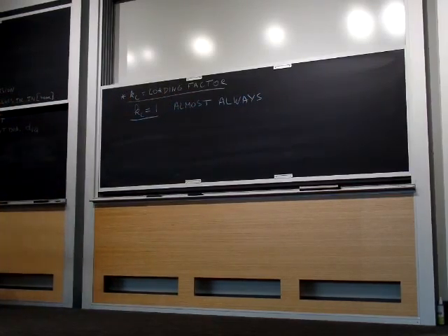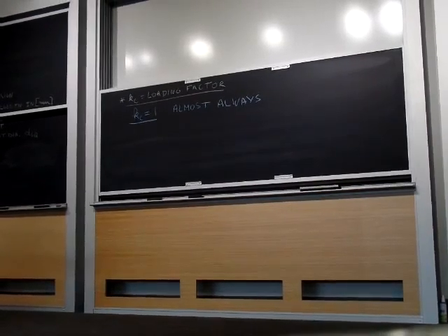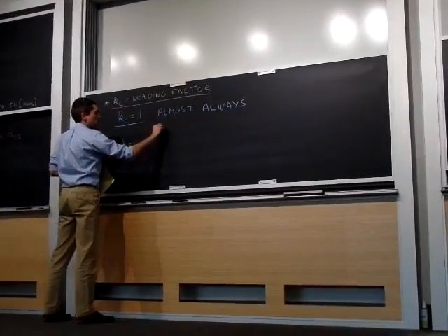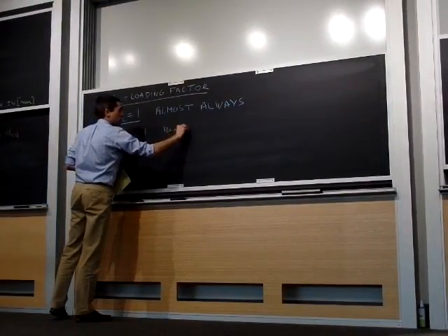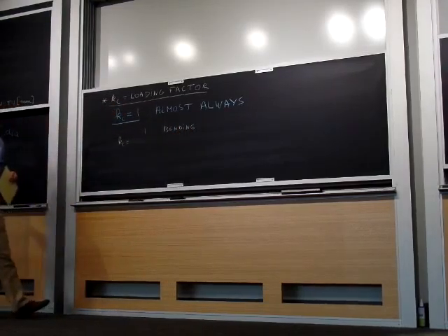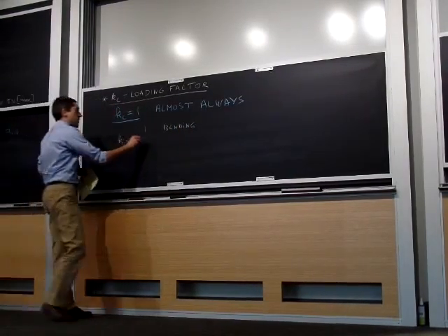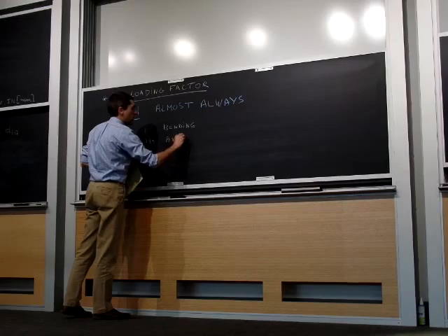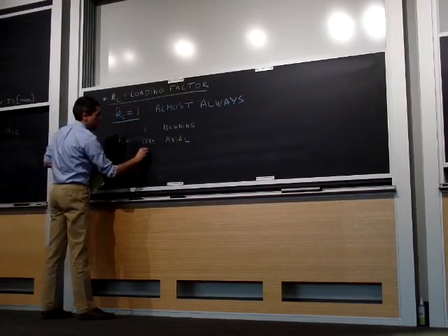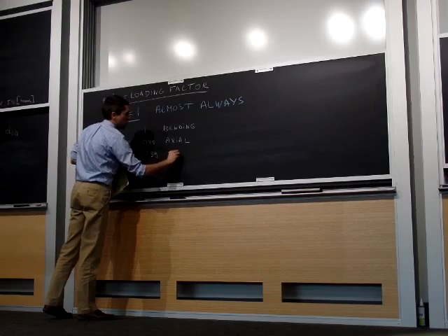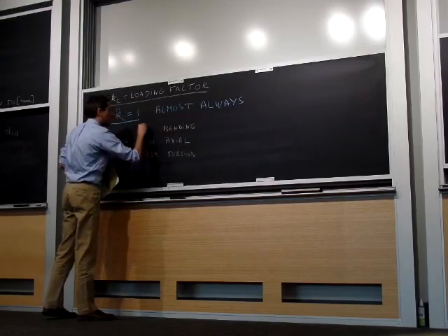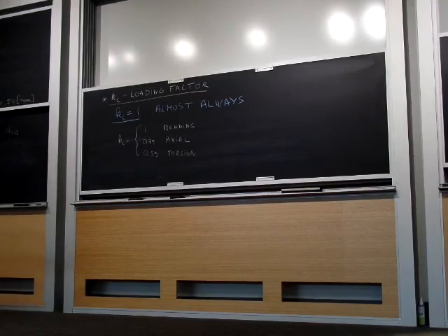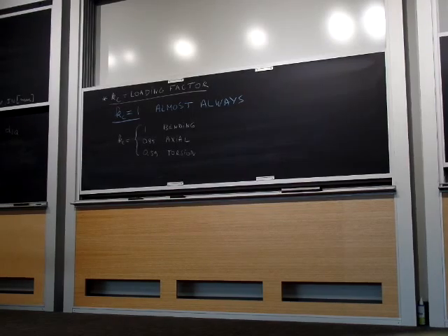If we scroll down in our formula sheet, you'll see that what it says there, KC is equal to 1 for bending loading, and what that means is pure bending. It's 0.85 for axial, and again that is simple axial loading, so pure axial loading without bending, without torque, and then 0.59 for torque. So if you ever are in a case where there is pure axial or torsion loading, which doesn't occur very often, then you can take KC equal to that value.